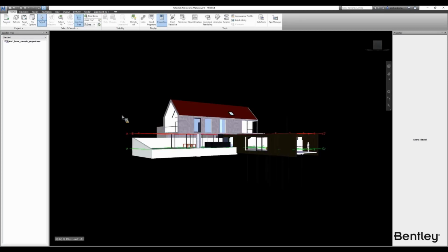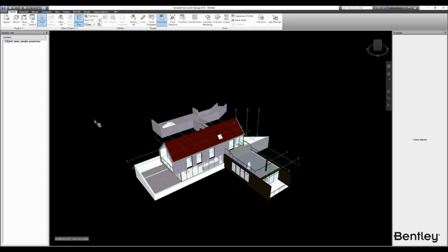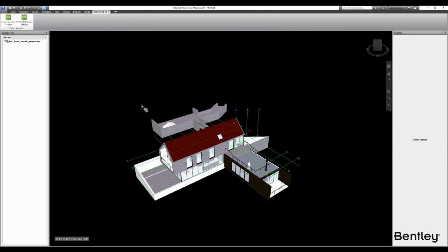So this is a pretty common stage. Everybody knows about this one, how to get your models in Navisworks. So the second part comes in. We have to install this SYNCHRO plugin. You can get that from the Bentley software download website, and we'll put that link up if required. But once you have the add-on installed, you see this export add-ins over here. So I'm going to click on SYNCHRO plugin settings.